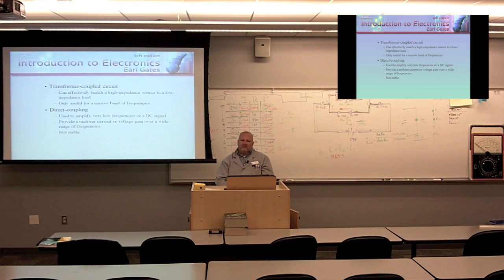Transformer coupled circuits. Sometimes we're going to use transformers to couple one circuit to another. It can effectively match a high impedance source to a low impedance load. Remember before in lecture I was talking about a high impedance microphone? If you wanted to couple a high impedance microphone to a low impedance amplifier, you could use transformer matching. You could have an impedance matching transformer that you could utilize. Why is that so desirable? So that you get maximum power transfer. And you always want to get maximum power transfer.